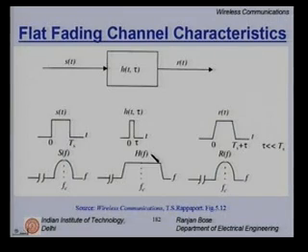What is important is that H(f) is much larger than S(f). So, Bs, the bandwidth of the signal, is smaller than the coherence bandwidth of the channel approximately. So, what we get is a product of these two here, and as expected there is hardly any distortion. This is exactly what happens when we work in a flat fading scenario.